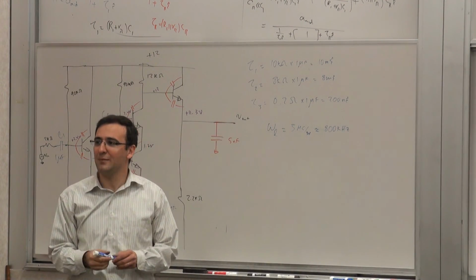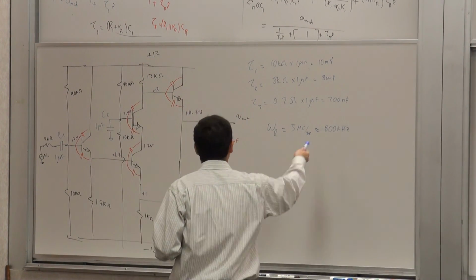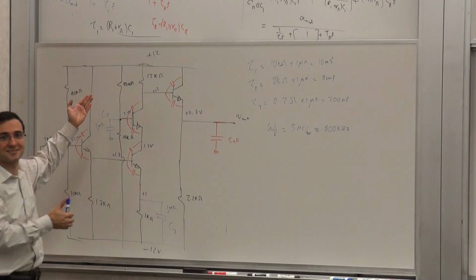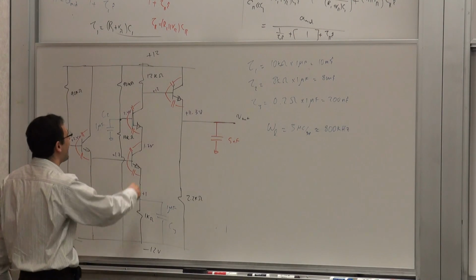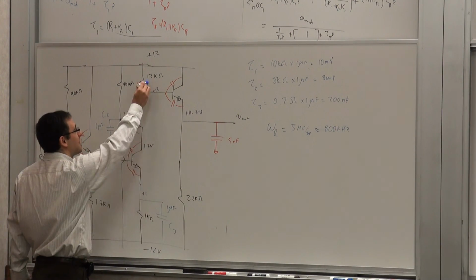If you're making an audio amplifier whose omega L is 800 kilohertz, nothing is amplified. Right? If it were an audio amplifier, what would you like your omega L to be? Ballpark, 10, 20 hertz, right? Tens of hertz, not hundreds of kilohertz. This is not going to work, actually. It's going to have very little gain. You've designed it for much larger gain, but you get the gain of basically this capacitor not being there.